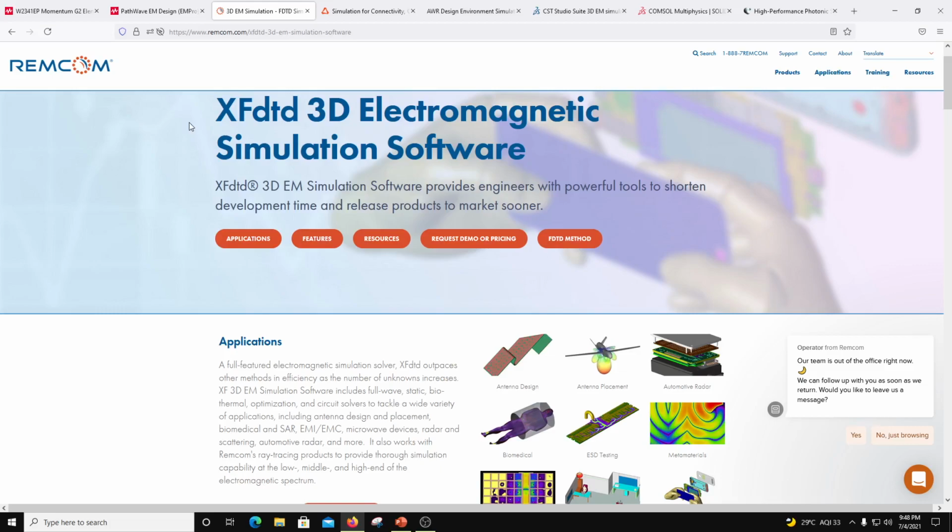So that's the absorbing boundary condition, right? That's the difference from PML. The PML boundaries don't have a thickness of a certain cell size, while in the case of absorbing boundary conditions, you specify a region around the cuboid box, the box which encloses the entire simulation design, and that box has a certain thickness of cells. So that is the absorbing boundary condition. Those things we will see once we do FDTD simulation.